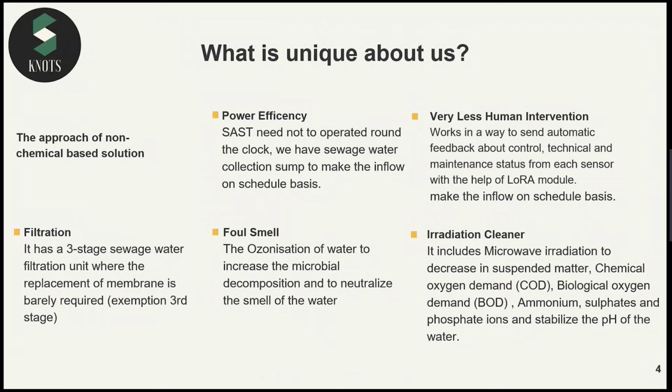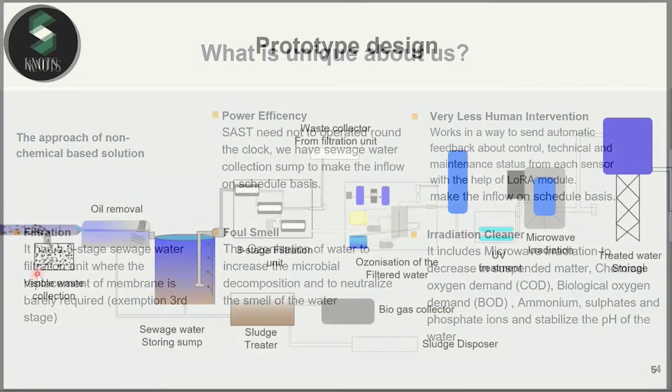Coming to the question of what we are doing differently: 1. We are adopting an approach of non-chemical based solution. Unlike ordinary treatment plants that work round the clock, our machine need not be operated 24/7. We have a sewage water collection sump where the water is stored until the sump is full, which is then indicated by a water level sensor that is fit in the sump.